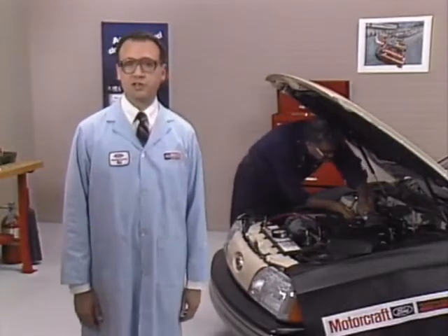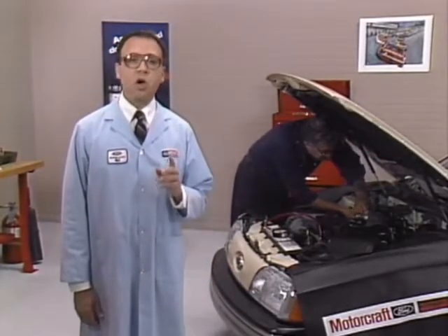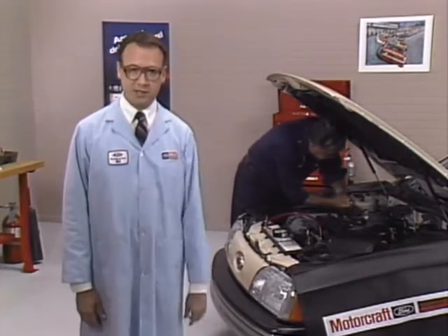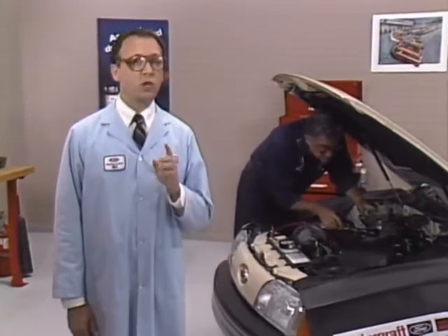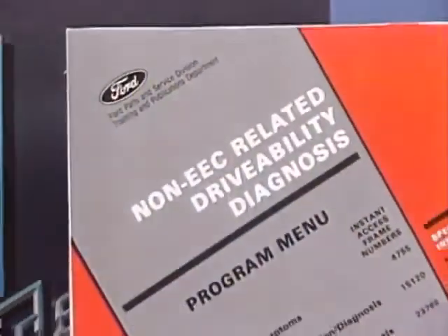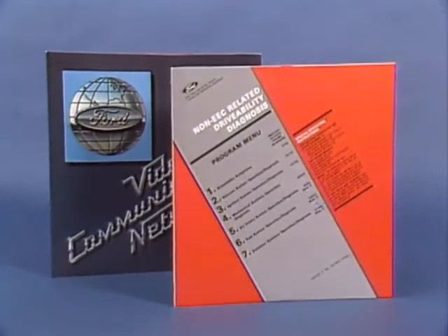Well, that takes care of pressure checks. But the fuel injection system also has to provide enough fuel flow for the engine to run properly under all operating conditions. Therefore, your diagnosis will often include not just a pressure check, but a complete pressure and flow test. The pressure and flow test can help to find fuel system problems such as leaks, blockage, and fuel pump malfunction. For more information on pressure and flow testing, refer to the shop manual and to the video course Non-EQ-Related Drivability Diagnosis Part 2. Now try some practice questions on fuel pressure checks.